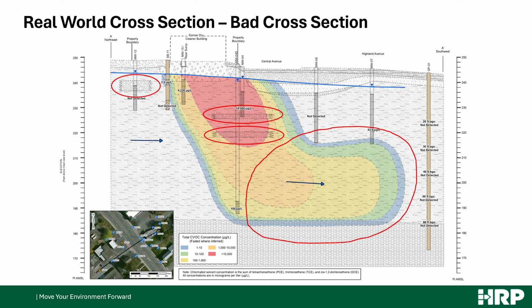The worst thing you can do is have a remedy that's not going to work. So if you have a subsurface geology that you don't thoroughly understand, and you propose to do some ISCO injection somewhere, and it isn't where the contamination is coming from or going, it's just going to be a complete waste, and it's not going to work. So we need to really understand the geology thoroughly so that we can get right-sized remediation options and really have a good understanding of where things are.